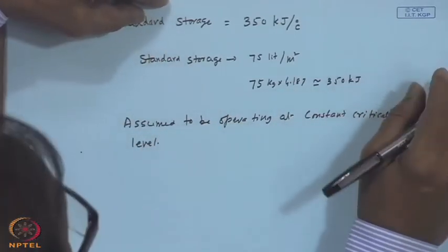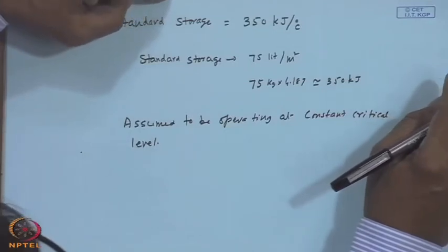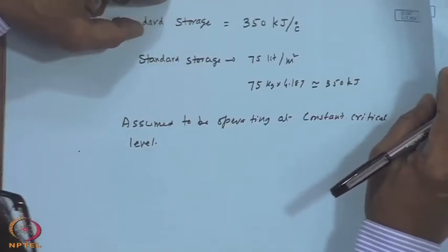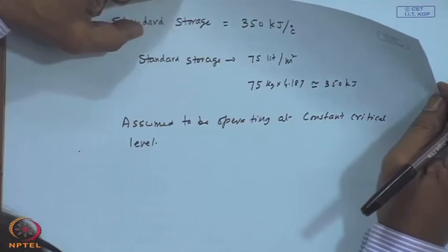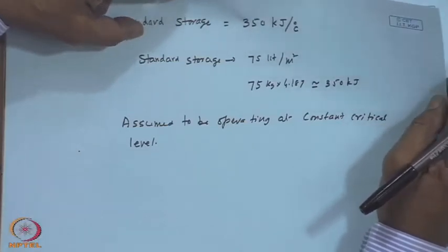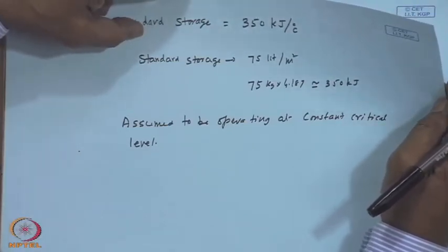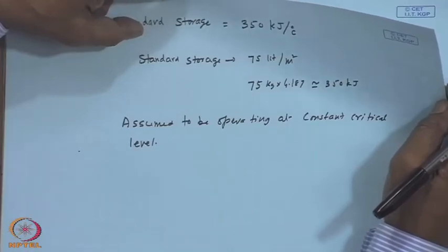So, you have a situation here: the monthly solar load fraction can be calculated for a system delivering energy at or above a certain desired temperature. The additional parameter that needs to be calculated is the monthly average daily utilizability, but the limitations are that storage can be taken care of, but the critical level is assumed to be constant.